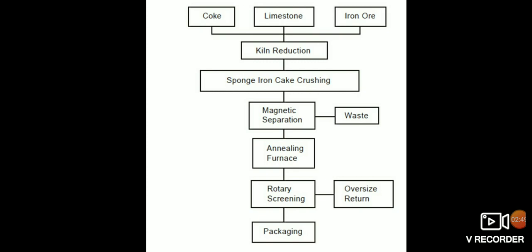The sponge iron is mechanically removed from the saggers, ground, and the resulting powder magnetically separated from the impurities. In a final reduction, the powder is carried through a continuous furnace in a hydrogen atmosphere on a belt made of stainless steel.